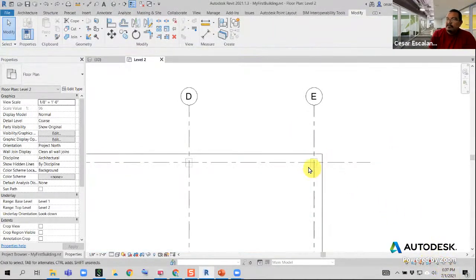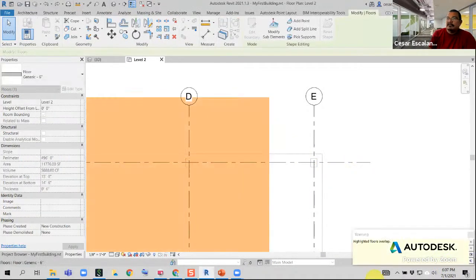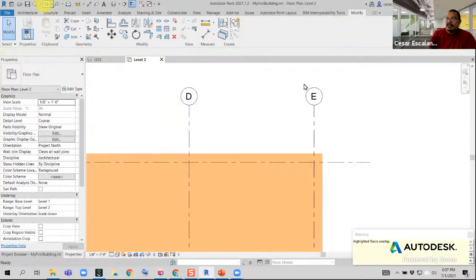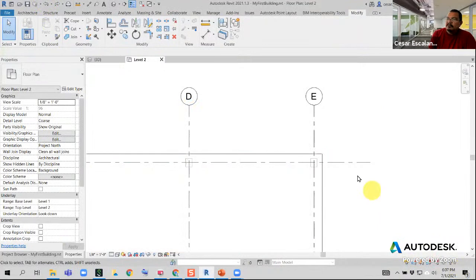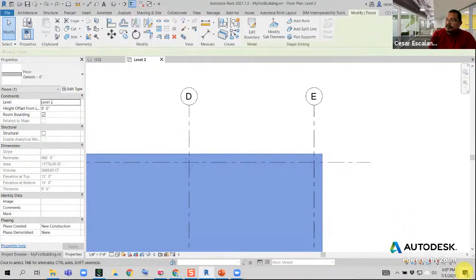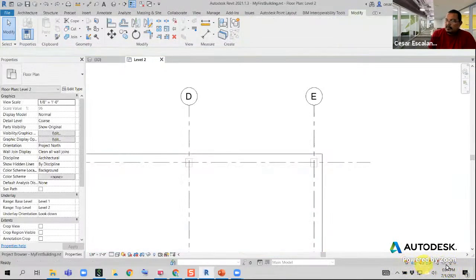So again, if I enable it, I hover over, I pre-highlight, click and drag. That is dangerous. I don't like that behavior. But if you disable it, and I select an object or pre-highlight an object, it doesn't do that anymore. And so for the most part, I would say disable everything by default. Then you're going to make sure that things that are pinned don't move, links don't move, objects don't move by mistake, and you don't select objects by face.